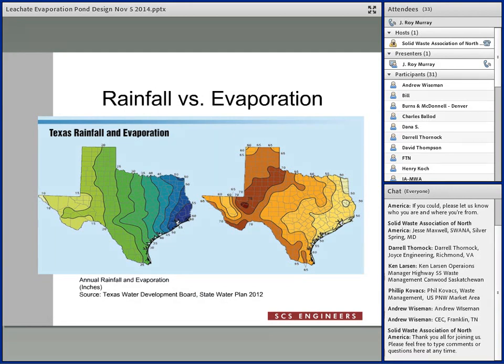And this is different because what they've done from the Texas Water Development Board is they have taken the pan evaporation that the National Weather Service reports and then converted it to lake evaporation based on additional information the National Weather Service reports. So you're going to be able to compare these two numbers and get what would be your net evaporation.